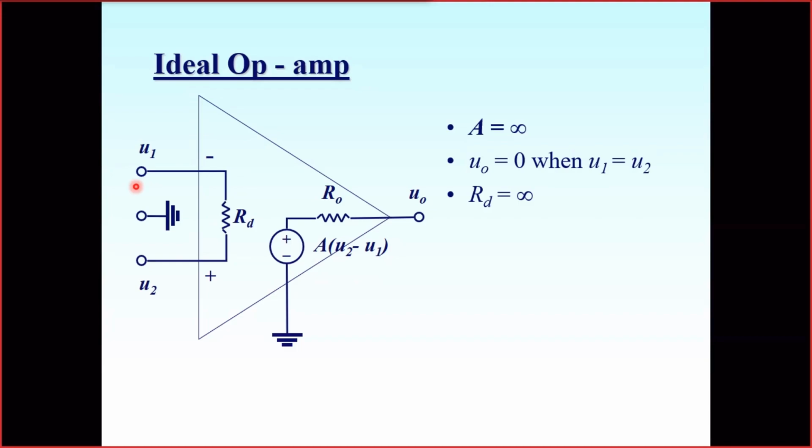It's not the case for a real amplifier, but it's very close because the actual input resistance of the amplifier may be as high as some gigaohms. Megaohms is absolutely normal, but in the implemented circuit, the input resistance may be effectively even higher, up to gigaohms.